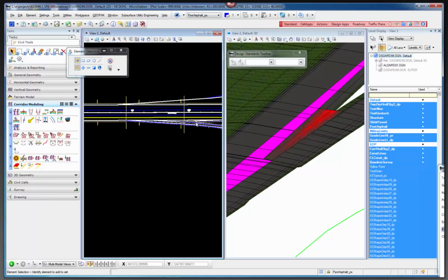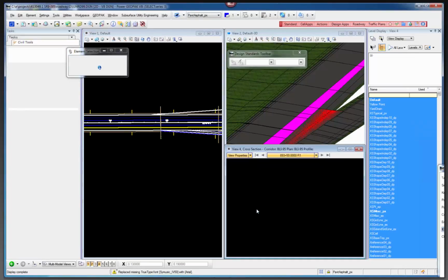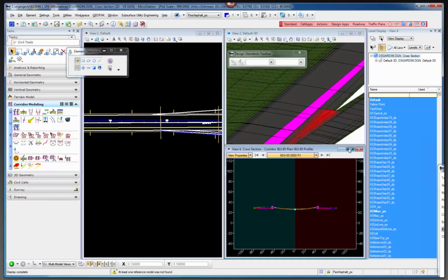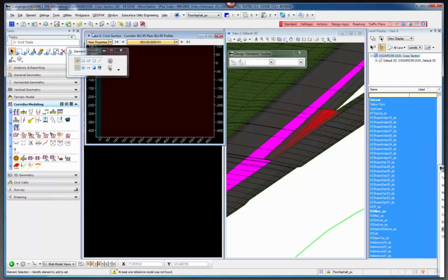But essentially, once you have that laid out like that, then you could use a clipping between there, but I try to stay away from the clipping. It adds a lot of overhead to the corridor, but it's still an option to use out there. So then if you just go to a cross-section view on this corridor, and I'll go ahead and expand it. I do want to kind of see where I'm at a little bit though.